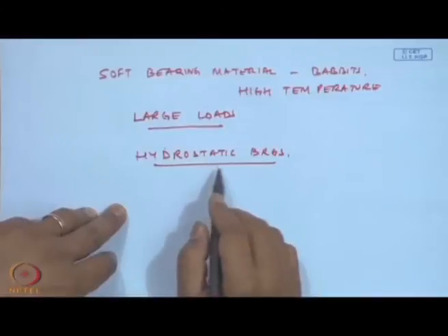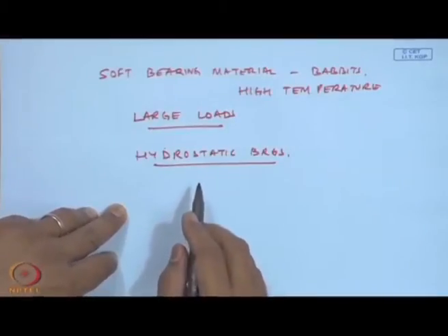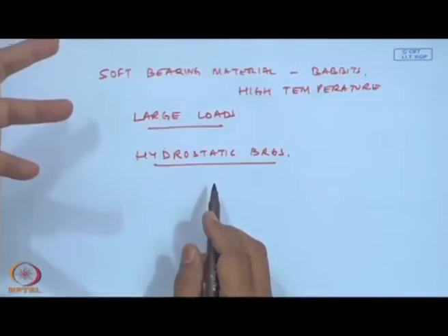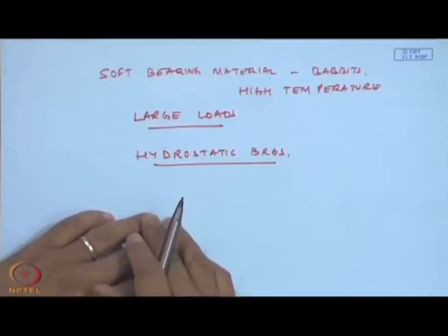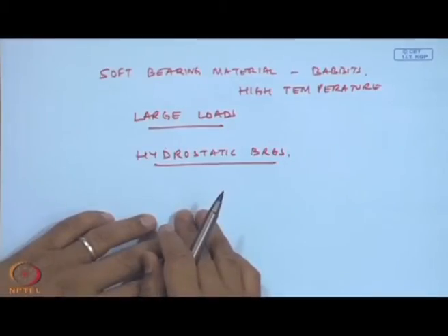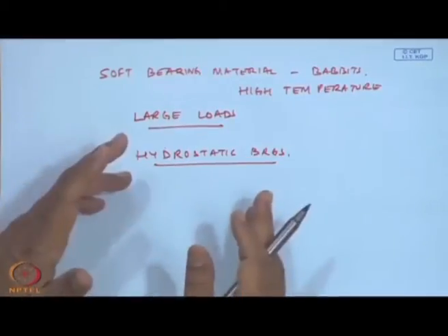But in our case we have the journal bearings or the rolling element bearings. In rolling element bearings, if I have some provision of adding a squeeze film damping arrangement in the outer race, wherein I can change the damping, which is there actually in aircraft engines. Other than the rigid rolling element bearings, they also have squeeze film dampers on the periphery, which will not rotate, but only oscillate, and thus create this damping. And as you know, because of the damping, the forces on the bearing support come down.